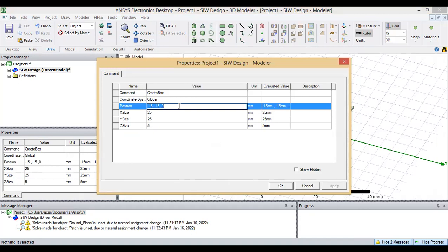How we can design using HFSS. So directly I'm taking some predefined values that I have already used in my papers. The length I have considered earlier is 24 cross 24. So I can give the coordinates like 12 mm, minus 12 mm. Then I should give it 0.787 mm, because this will be placed just above the substrate.